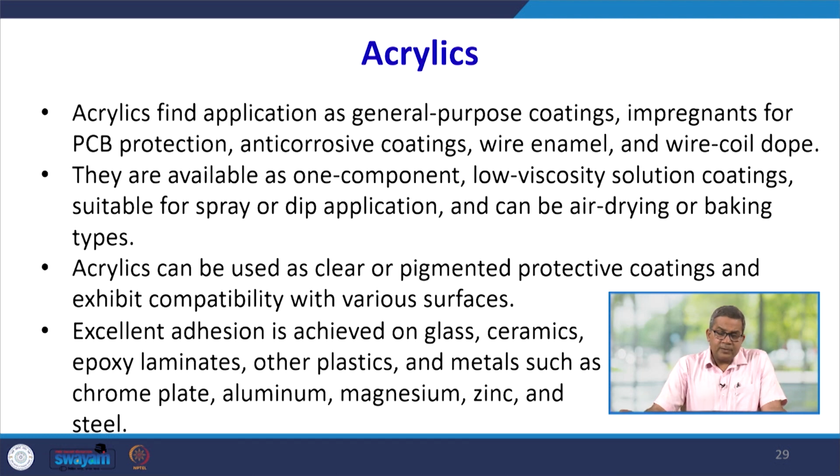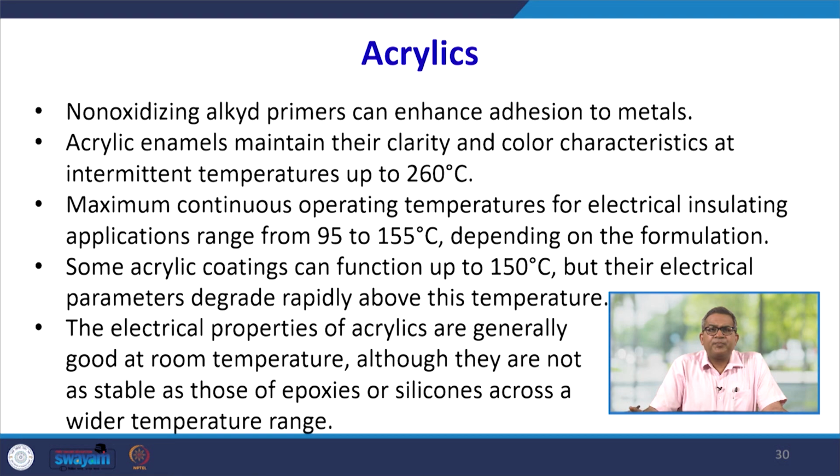These acrylics can be used as a clear or pigmented protective coating and exhibit compatibility with various different types of surfaces. Excellent adhesion is achieved on glass, ceramics, epoxy laminates and other plastics, and metals such as chrome plate, aluminum, magnesium, zinc and steel.